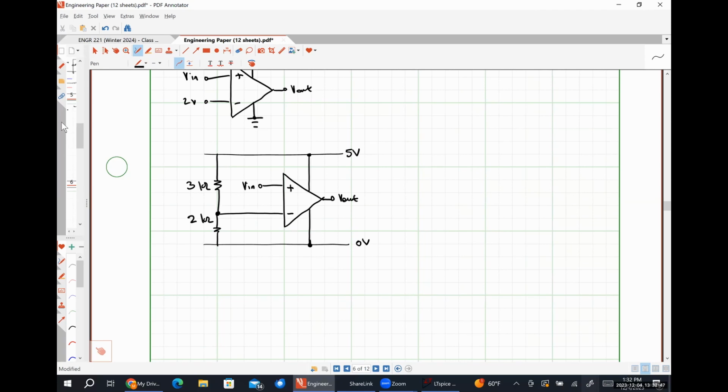For this one, so this stuff is going to be for homework. This thing right here, with a gain of 12. So make this exact curve 12 times bigger for part A. This peak value of 1.5, what's 1.5 times 12? Yep, 18. Is 18 less than positive 20 volts? And then we have a peak negative value of negative 1.5. Is negative 18 less negative than negative 20? It is not. So it's literally just going to be this exact curve, but scaled by a factor of 12.